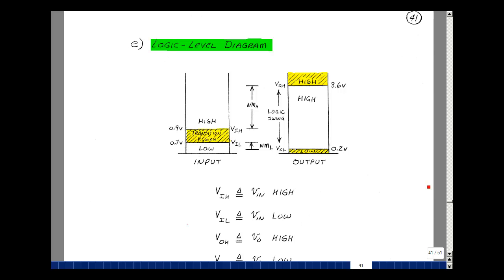Electronics is exposed to all kinds of noise, from cell phones, from motors, things that radiate energy. The logic gate needs to be able to withstand noise. And we're going to find this next term called noise margin high as a measure of this. That's going to be the difference between these two numbers. What this means is that if this is the output of a logic gate, and that now becomes the input to another logic gate, how much noise can I tolerate before the logic gate changes its function? Let me do some numbers here. Suppose I'm sitting at 3.6 volts at the output of a logic gate, and now hook this up to another logic gate. How much noise could I have before I change the function of it?